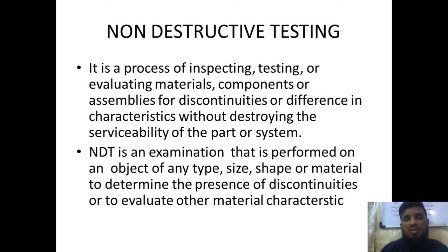The main advantage is that in this process we are able to identify the discontinuities or the defects without destroying the serviceability of the material. For example, if you are using a connecting rod in your automobile, and suddenly you wonder whether the connecting rod you are using is a good one or not, by using non-destructive testing you can check whether there are any flaws in the connecting rod, directly while it is in service itself.